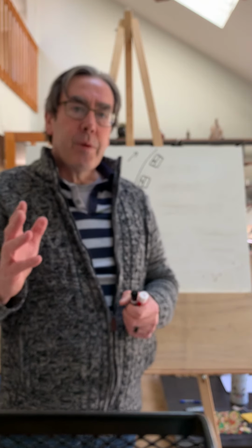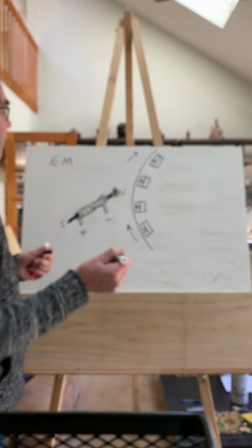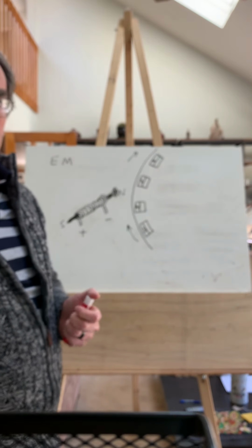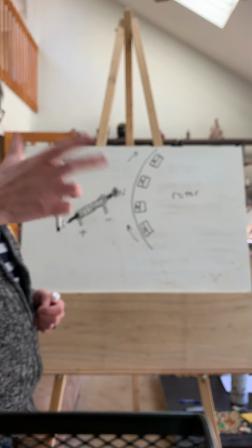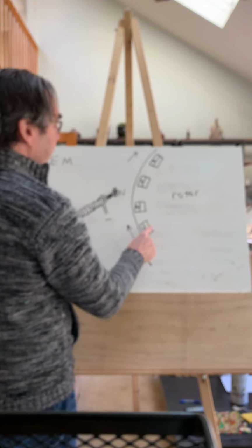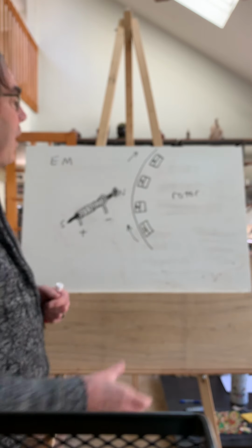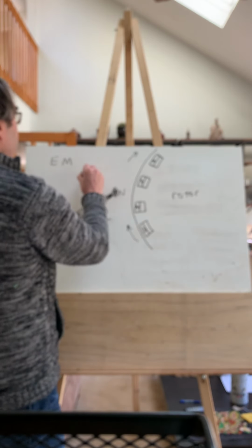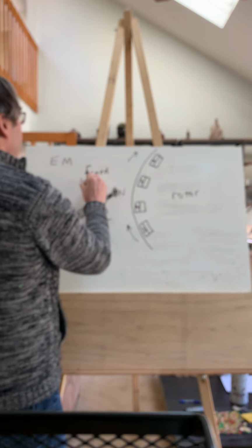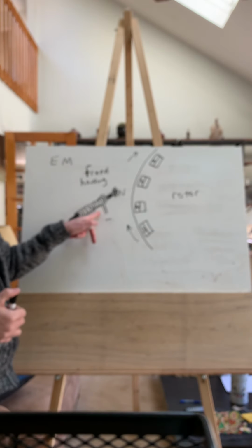And if we can do that with sufficient precision, we can get that thing rotating at almost any speed that we want. And so the minimal parts of a working motor are, first, you need what's called a rotor. And that's going to be some part that's free to rotate. And on that are going to be fixed permanent magnets in alternating polarities like that. Now, it's also possible to put the electromagnets on here. But then you'll also need a fixed housing to which is attached an electromagnet that can switch polarity.